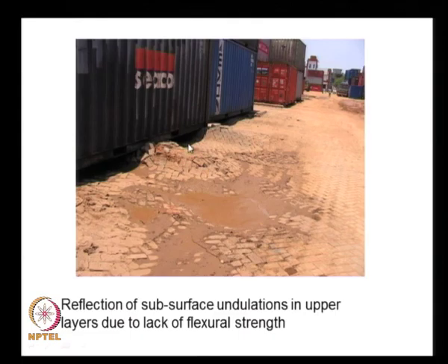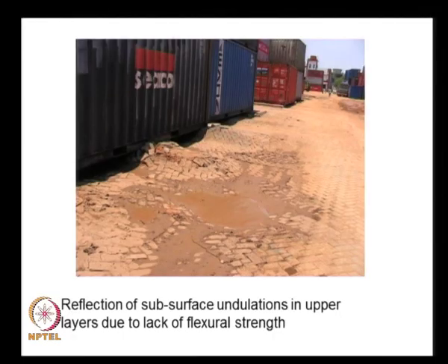And our objective in constructing these pavements is that this type of reflection does not happen. Whatever undulations are there in the layers below, they should not be reflected to the top surface, because once this happens, the rideability decreases and we cannot use this surface anymore.